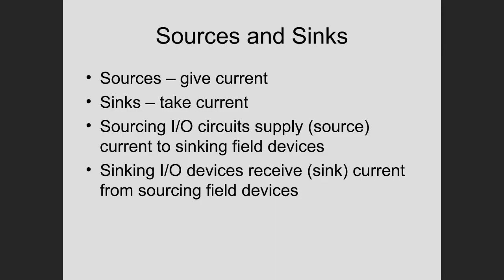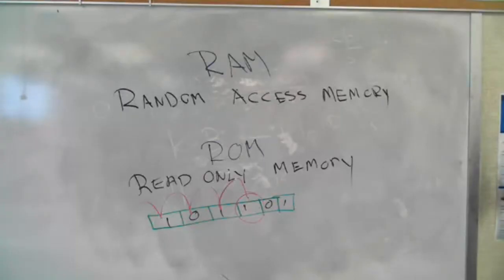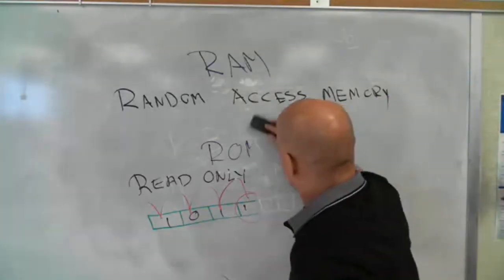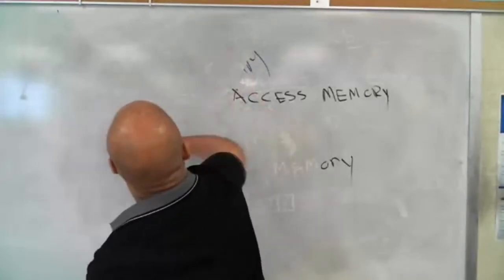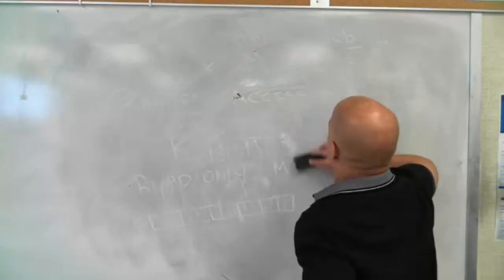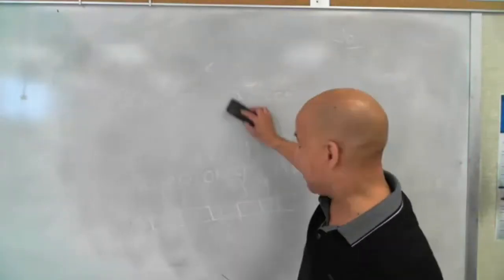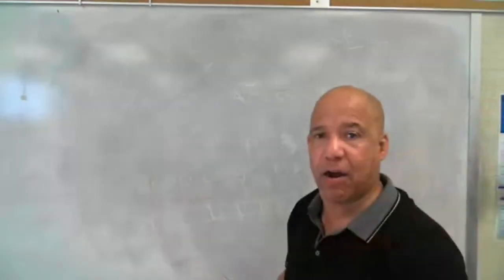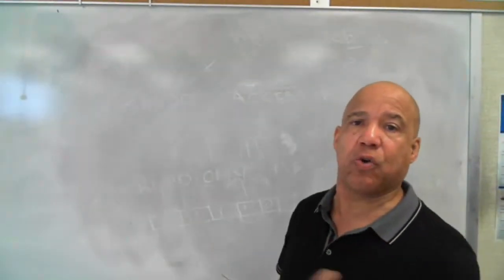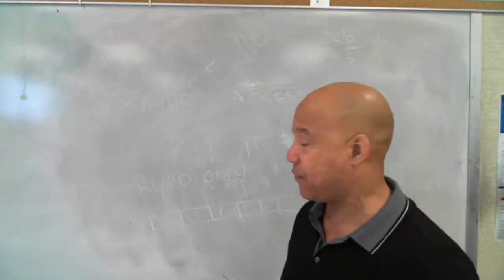Now, somebody asked about power. Let me go up to the camera. I'm probably going to run out of time here, and I'll have to pick this up on Friday. So power in the PLC, it just depends. In general, in electricity, we have something called a source or a sink. Think of plumbing. Think of a sink. If you're going to sink current, something's going down the drain. If you're going to source current, something's coming out of the faucet.